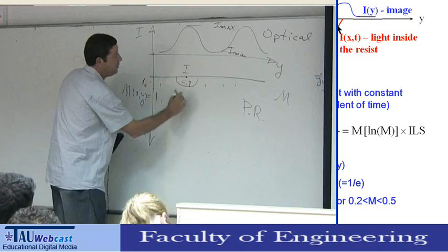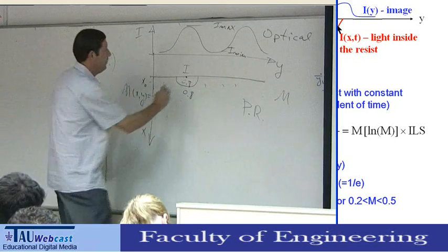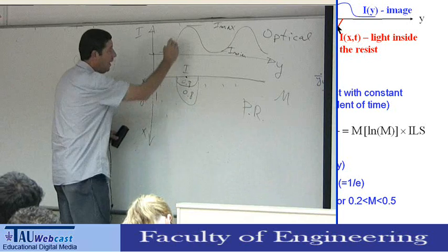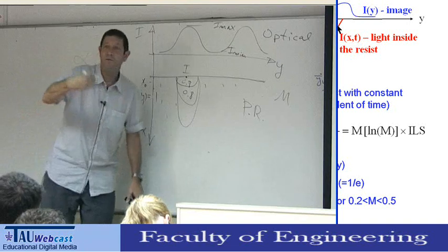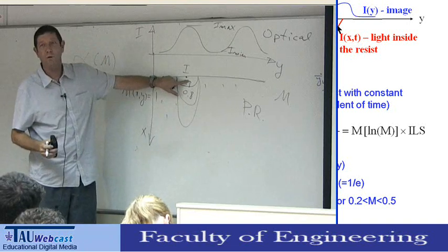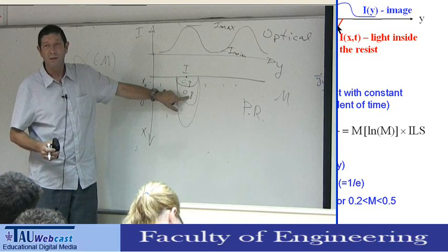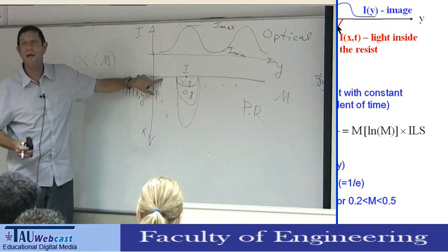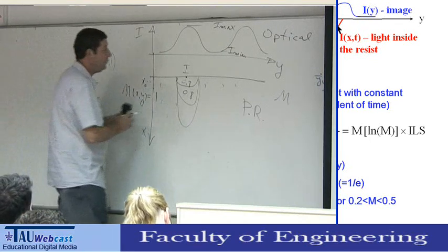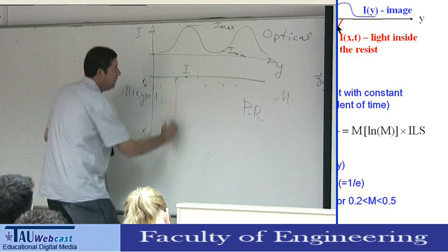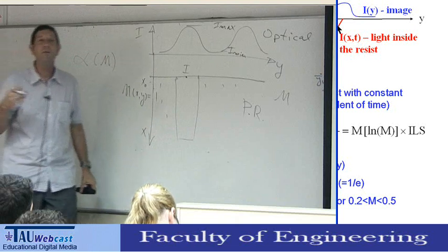So in the area below it, we start to decompose, we start to destroy the photoactive compound. And then what happens is that under the illuminated region we have some positive feedback mechanism, because here we destroy the photoactive compound, the photoresist becomes more transparent. That's why we get more light here. On the other hand, here we have very little light, so here the photoresist is not transparent. So after a while, we destroy most of the photoactive compound in this region. And this is a very nonlinear effect.